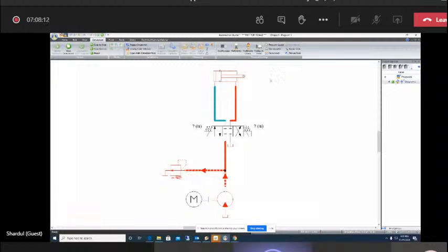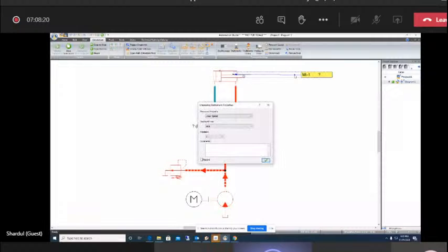So what you can do here, you can just click on the first measuring instrument, component dynamic, click on the cylinder, just drag it here, and it will ask you which property you want to measure. So let us say you say linear speed of the cylinder. You can also select the unit you want, centimeter per second, meter per second. You can also select the precision level.